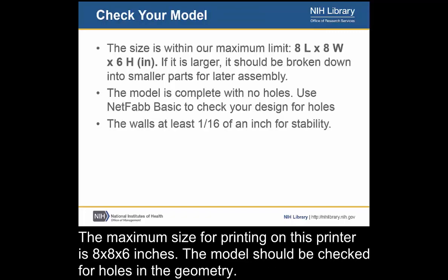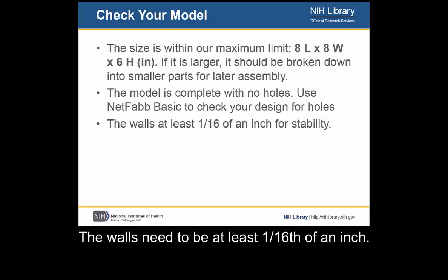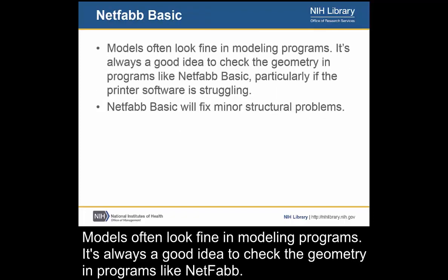The maximum size for printing on this printer is 8 by 8 by 6 inches. The model should be checked for holes in the geometry. The walls need to be at least 1/16 of an inch. Models often look fine in modeling programs. It's always a good idea to check the geometry in programs like Netfabb.